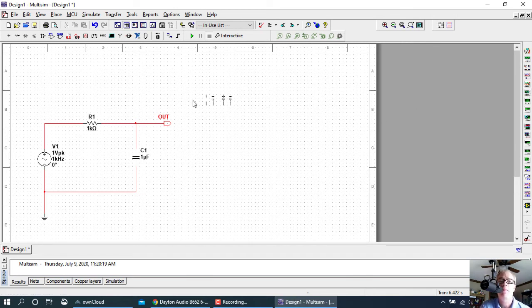So let's bring in the Bode Plotter, and let's put it right here. And you'll notice, let me drag it over here. You'll notice it has an in and an out, an input and an output. You think that's an output, but it's really not. Both of these are inputs that come into the Bode Plotter, but it's kind of telling you that it needs the input signal here and it needs the output signal here. And then there's 2 positive terminals and 2 negative terminals. Those negative terminals, go ahead and tie them to ground, both of the negative terminals, and you're done with those. Just like that.